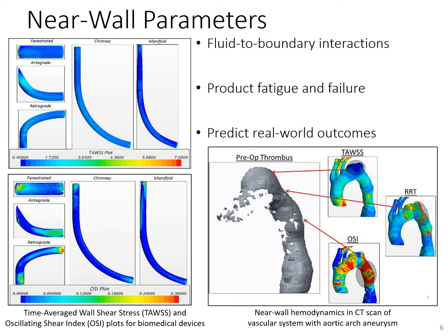Additionally, another parameter of relative residence time, which is essentially a measure of the combination of low wall shear stress and high oscillating shear index, also predicted another pocket of thrombus accumulation that was shown in the patient scans. This provided some verification and validation of these parameters as useful computational predictors of real-world clinical outcomes.